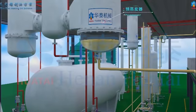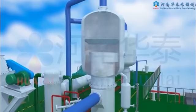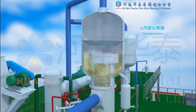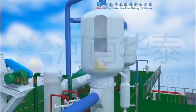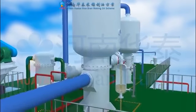The pre-evaporator is heated by the solvent gas heat from the DTDC. The mixed oil presents a rising film state when it goes through the stainless steel tubes. The solvent gas is separated by the vapor-liquid separation on the top of the pre-evaporator. After the first concentration, the mixed oil goes into the temporary storage tank.